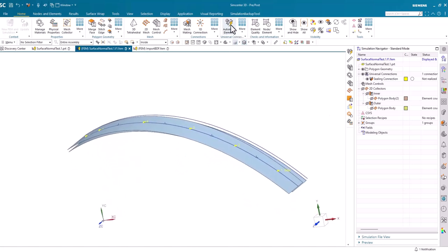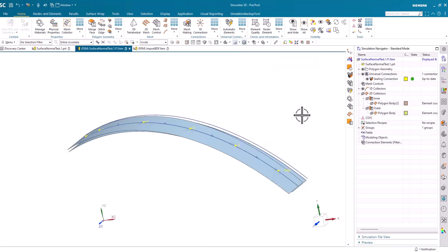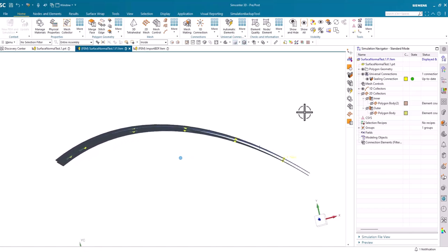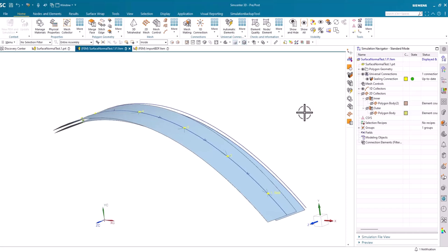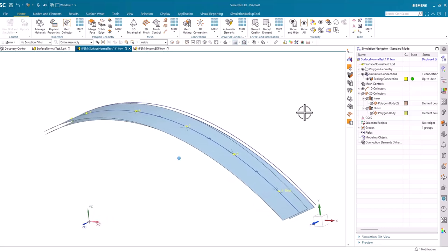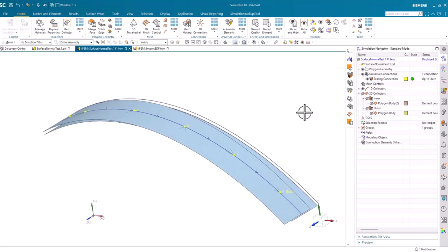Then same process. Go ahead and create these as springs and RBE3s if that's what you want, and go ahead and say OK. And then in the end, I have the same situation of uniaxial spring elements with local coordinate systems. The uniaxial direction is going to be the y direction. The in-plane perpendicular directions are x and z. Those springs are connected to the flanges with spider elements.